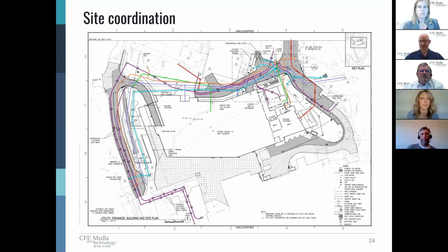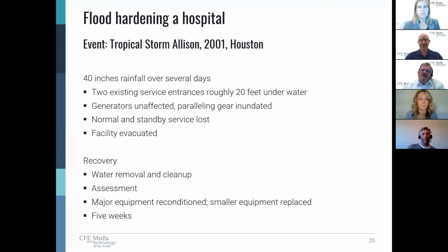And so during this process, since we had to relocate feeds for 7 buildings, we have to coordinate all of those outages, and the importance of coordinating that with the facility and making sure the owner is aware of the impact for that and how they plan on addressing that and what time of day they want to do all that. So all of this is extremely important, and having numerous coordination meetings to ensure that we don't, especially for critical care facilities like healthcare, cause a problem, and everyone is aware of our outages and when they will occur.